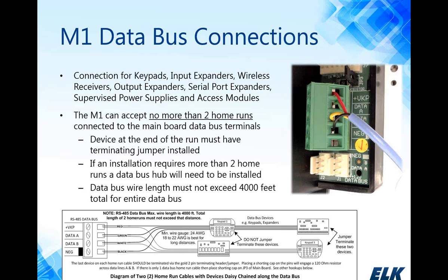The data bus wire length cannot exceed 4,000 feet. So that's for the entire bus. So you have to do that calculation of how far each run of wire is taking you, and make sure that that does not exceed 4,000 feet.